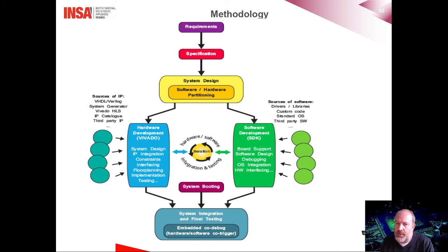The methodology here is quite similar to the previous methodology that we studied. After describing the requirements and the specification of the system, the system design step consists in partitioning what is going to be implemented in software and what is going to be implemented in hardware. The hardware development is performed using Vivado, as we've just seen. All system design, IP integration, interfacing, flow planning, implementation, and test are performed in Vivado.